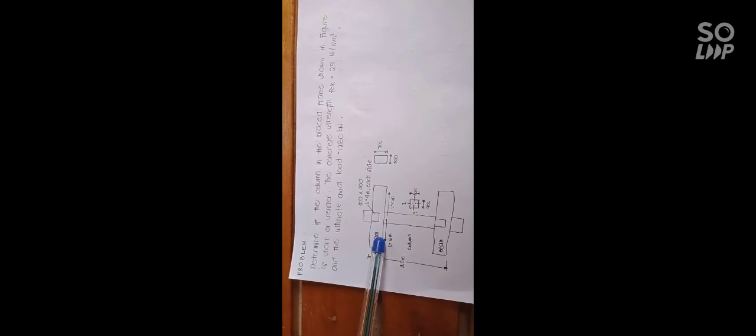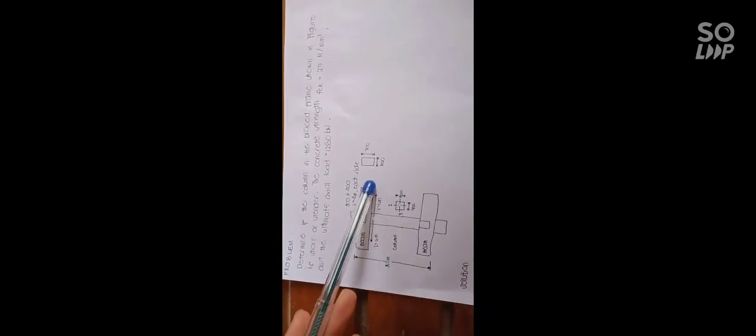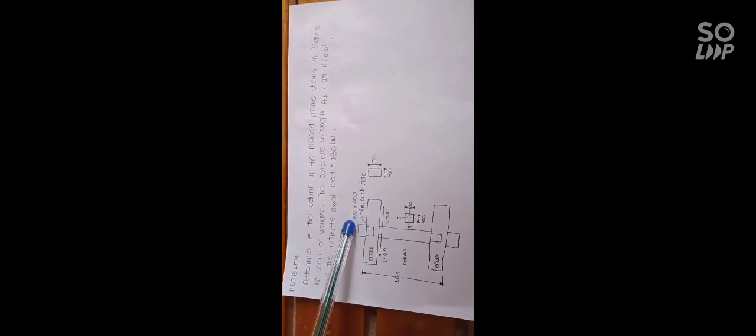We have a beam of the same length, and the lengths on each side are 6 meters and 4 meters. The beam size is 300 times 700. The incoming beam is 300 times 500, with a length on each side of the column of 4 meters. We have the cross section of the column here, 300 times 400. So we go through a series of calculations to determine the effective height of the column and the slenderness ratio, to figure out if it is short or slender.